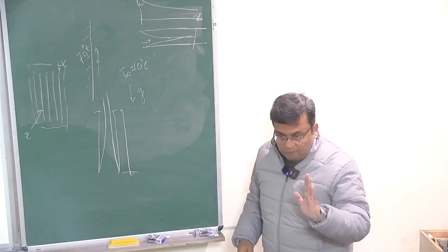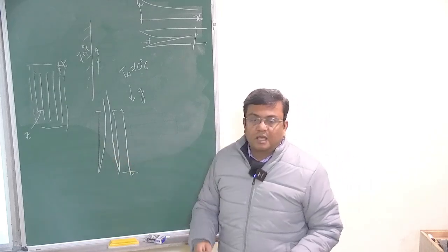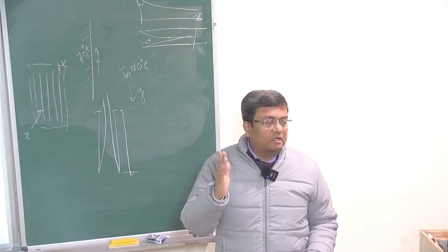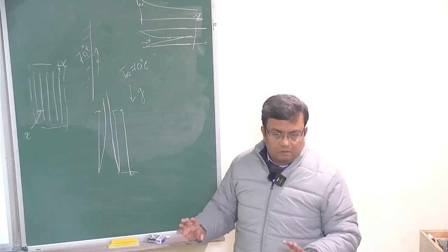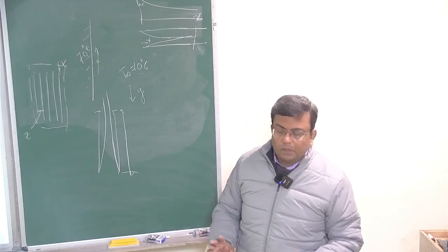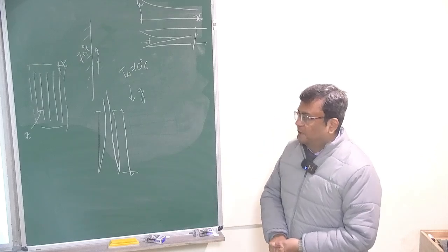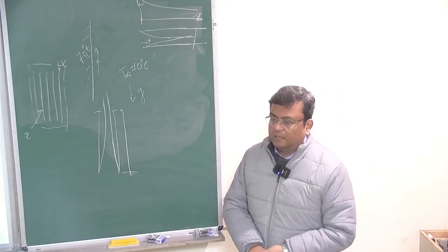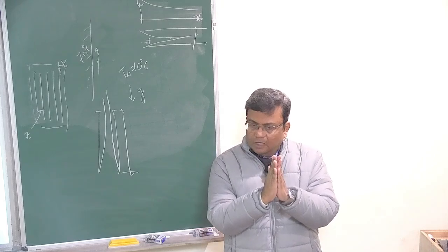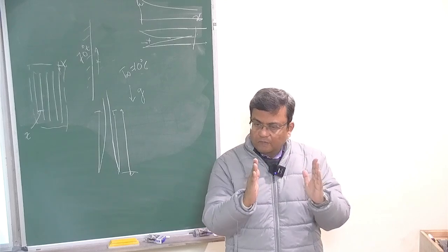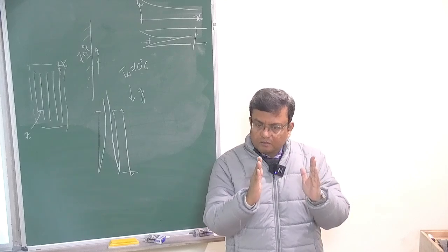Okay, so if the distance is large, then each fin surface like this acts as an isolated vertical plate. Okay, and the heat transfer is typically good. Now, what we will say is that if the distance is really small, the flow gets affected. If the distance is large, then for that channel heat transfer can increase.